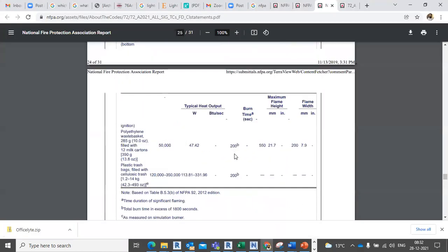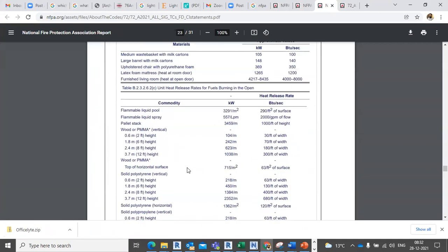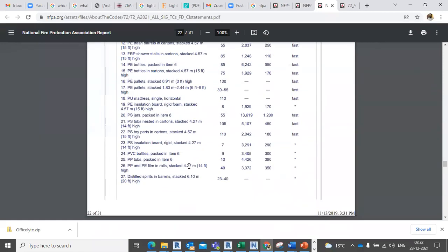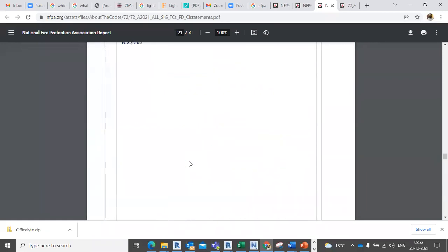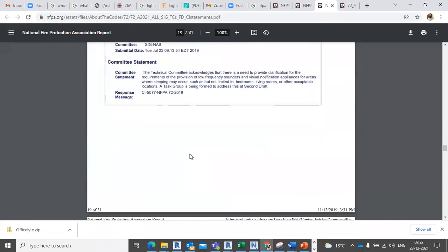I need to check. Shall we put heat detector also? Because depending on what kind of space we have, either we use smoke detector or flame detector or heat detector. Rarely we put both of them together. So I hope you're getting my point.